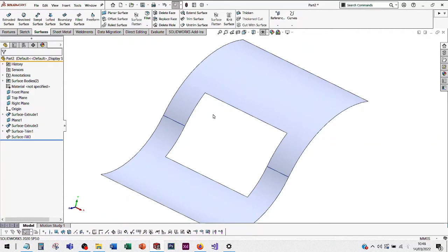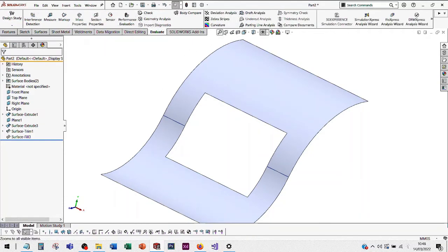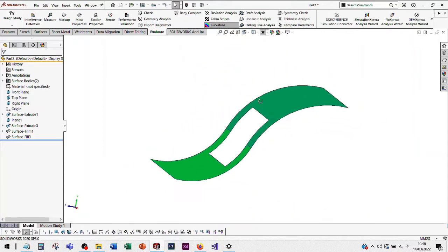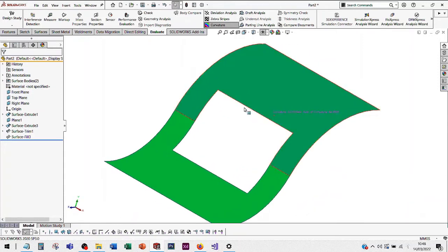The other thing to note just before I do that is if you click on the Evaluate tab and have a quick look at the curvature plot, we can see without cutting this away, we'd have to achieve a blend between the two. So to begin with, we'd have to try to reconstruct the green patch correctly, and then this lime olive green color surface correctly, and then we have to do something in the middle whereby we create the perfect blend between the two.